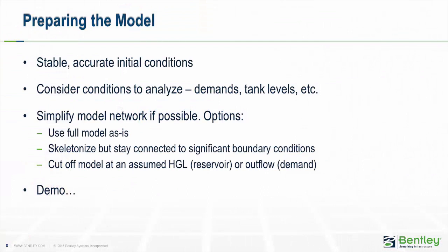Okay, so what do you need to do to prepare the model? So if you have a WaterCAD or a WaterGEMS model, first thing is you want to make sure that it's in really good, stable conditions. So, make sure it's calibrated. You don't have any issues with the model being unbalanced, or any issues like that. Hammer is a little more sensitive to those kinds of things than you can sometimes get away with in a WaterGEMS model. So you want to make sure that your initial conditions are nice and accurate.